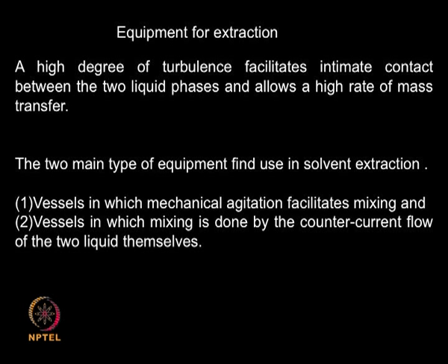Okay. Two types of equipments predominantly used are equipments which have mechanical agitation, and equipments which do not have mechanical agitation, but there is a counter current intimate mixing between the two phases which creates the turbulence and mass transfer movements. I will show you some pictures of many equipments which are used in industrial scale liquid extraction processes.